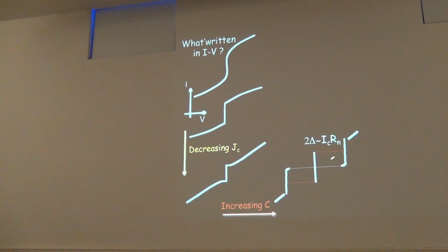So this is the effect of the capacitance. We have a bistable state, and we have the supercurrent here. And if you are around here and you increase current, you switch to the normal state. Obviously, this is the perfect ideal niobium junction that you get for low JC values. But these are relatives of this one, where you may have some kind of sub-gap currents around here.